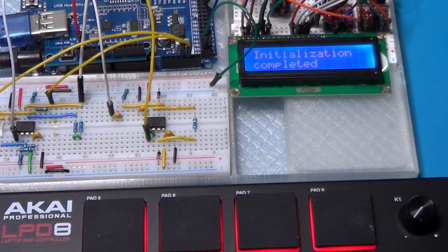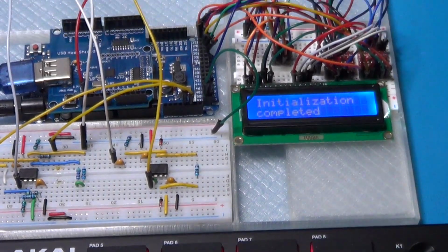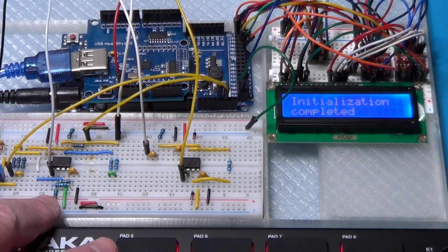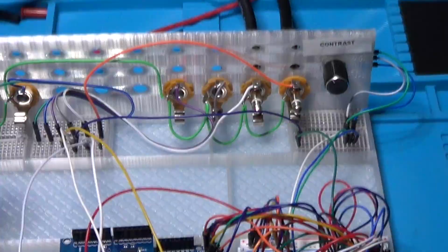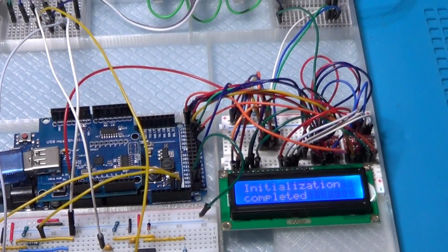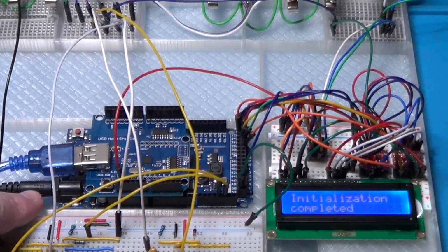of the Synth. The whole circuit is powered from 2 different sources right now. One is a dual power supply that powers the op-amp's circuitry, coming from this benchtop power supply unit. The other one is a 9-volt power brick that plugs directly on the Arduino. It is worth noting that this is only a temporary solution. The MIDI module will be powered directly from the power rails of the Synth rack, and the 9 volts needed for the Arduino will be locally derived from the plus 12 volt available on the corresponding rail.